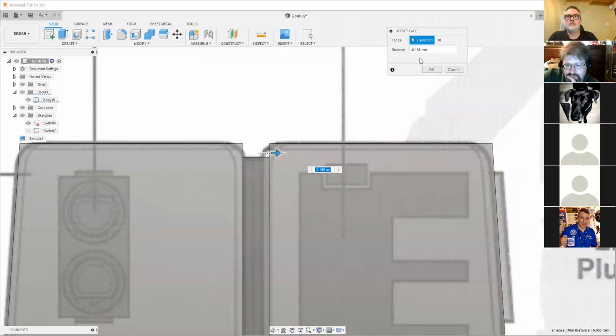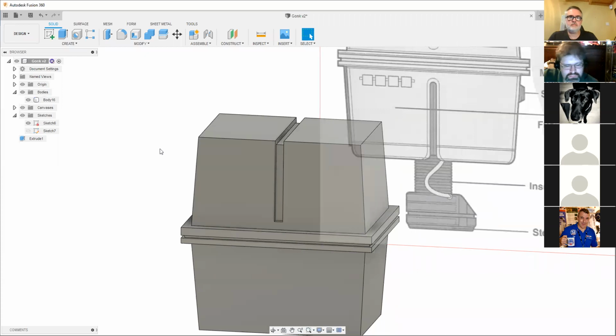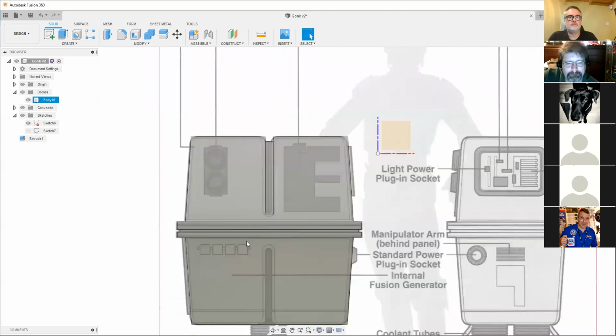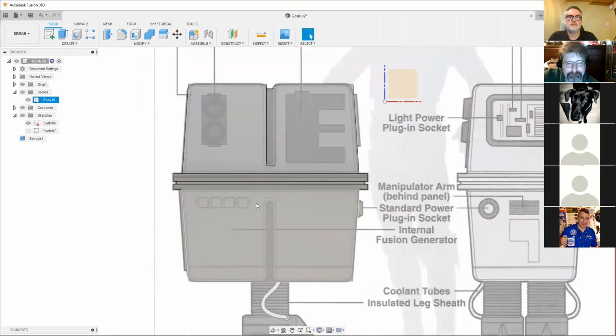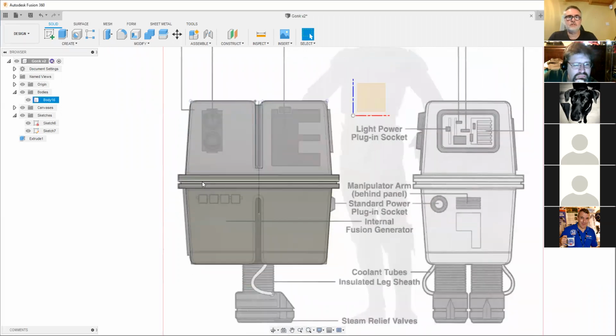Okay. Michael, maybe it's just me thinking ahead, but if we have this slot that's in the top and the repeated slot that's in the bottom, what would have stopped us from drawing a line across the center of the gonk? After we mirrored from left and right to get the top cut, mirroring it from top to bottom, so we have the same cut on the bottom of the Gonk Droid, and doing the push-pull to do both slots at the same time. Yeah, you can do that.